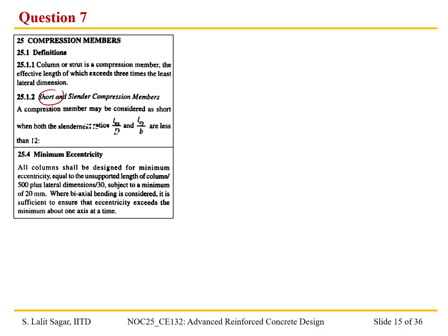Let us determine the eccentricity of the column. For the eccentricity, let us find out the minimum eccentricity first, as per clause 25.4.